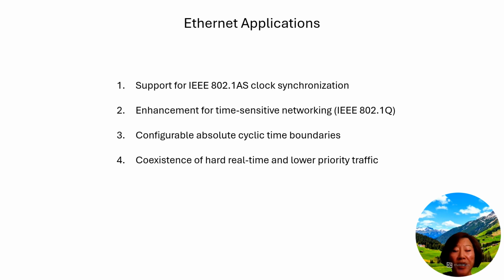Integration with industrial Ethernet systems often requires the 5G system to appear as a transparent bridge from the perspective of the TSN network, time-sensitive network. This involves techniques like TSN stream adaptation, where the 5G system maps TSN streams to appropriate 5G QoS flows, and TSN configuration adaptation, where TSN configuration parameters are translated into 5G system parameters.